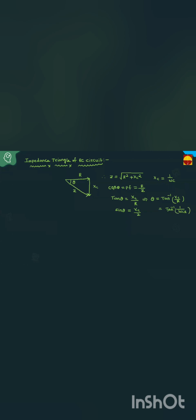Once you know the impedance triangle, how to draw the power triangle? Just multiply every vector in the impedance triangle with I square. Then you can get the power triangle. If this is resistance, multiply with I square, that is I square R. This is equal to P, the active power. This is XC, multiplied with I square, I square XC, that is QC. And this is which one, students? I square into Z. This is equal to the apparent power or complex power. And this angle is theta.